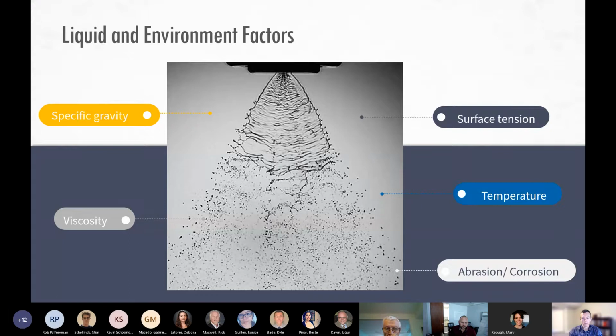Dr. Kyle, if you could speak a little about the relationship between viscosity and surface tension and why it's important to understand that distinction. Right. Understanding how a spray is developing, in terms of the characteristics on the previous slide and based on the material properties or rheology of the material, is going to be very important. Drop size in particular dictates how well distributed the spray is, and small droplets will coat a surface more uniformly. If you're spraying onto a conveyor, maybe in the paper industry, that would have a very important effect on how uniformly or non-uniformly you're coating your substrate. In addition, smaller droplets are going to evaporate and interact with the environment more quickly.